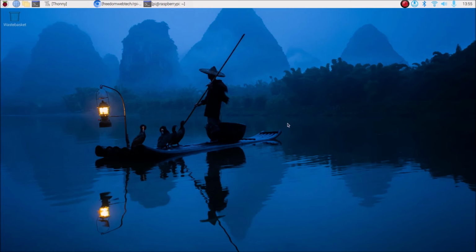We are going to follow the same steps which we did in the last session, but here we are only going to use the Raspberry Pi 4 camera module and detect the number plate in real time. Also we are going to use PaddleOCR for reading the text from the number plate.